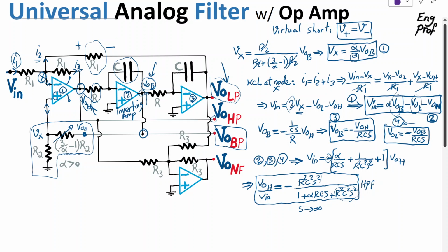And the way it works is, if you form the Bode plot, let's say the magnitude Bode plot, on the x-axis we have omega, and on the y-axis we have 20 log magnitude. In that case, you would see that at S equals 0, we are dead. Basically, it goes to negative infinity, indicating that it's not letting the DC and low frequency stuff pass. But the moment we are past that point, it starts going up at 40 dB per decade.